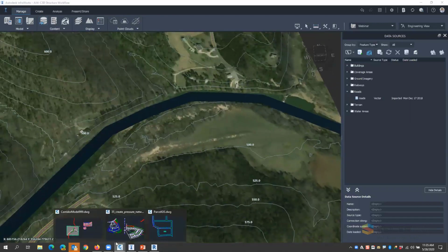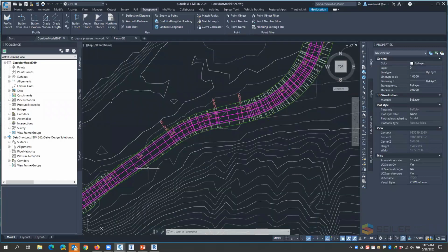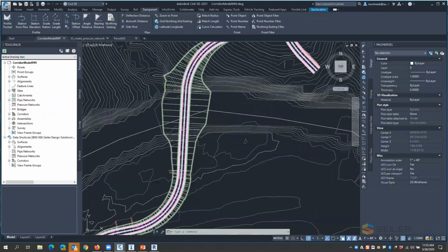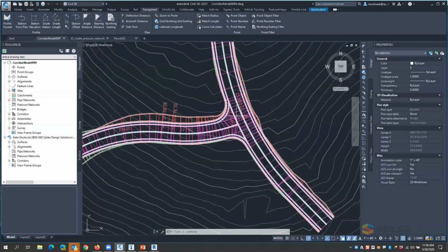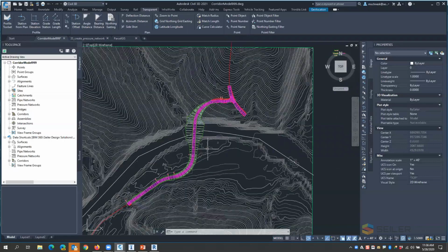So if I switch over to Civil 3D here, I've already gone through and made an initial corridor design. I pulled this information into Civil 3D from Infraworks. If you're aware of it, you create your model builder and bring your data into Civil 3D. I've got just a simple 2-lane road with 4-foot shoulders and a cut fill slope to the existing surface crossing the river here. I did my initial runs plus an intersection that ties into that existing road to the northeast. So this is just a standard corridor model.